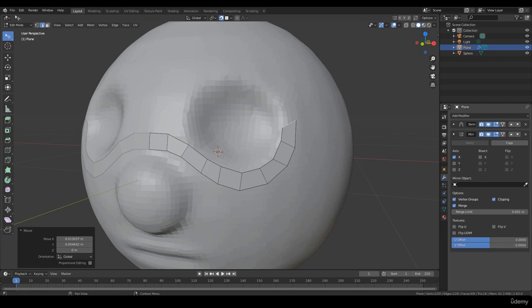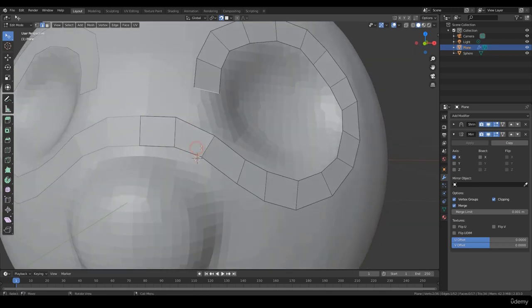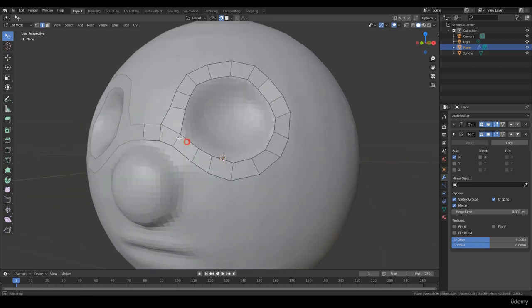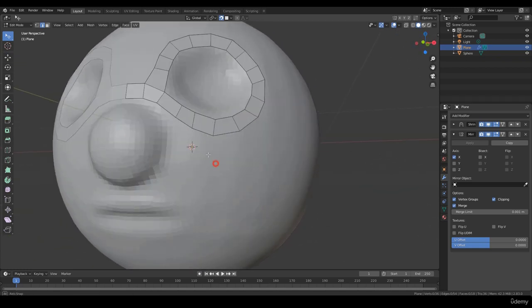A fast way to create geometry all around: as you already have a face here and an edge, with the edge selected, you can hold Control and then just right click, and then you can have it go all around. Control, right click on the mesh. And let's say you want this to snap here on this edge. You can select this edge, and press F on your keyboard to bridge. Okay, so F to bridge, another important tool that you can use.